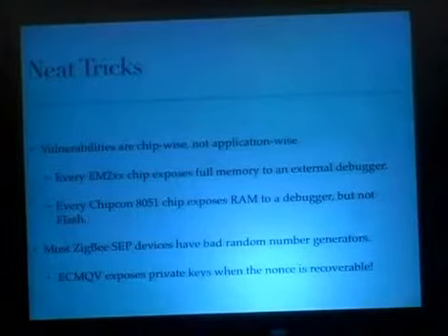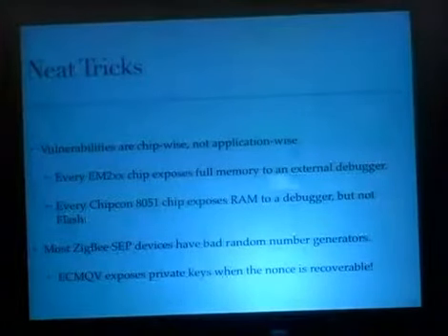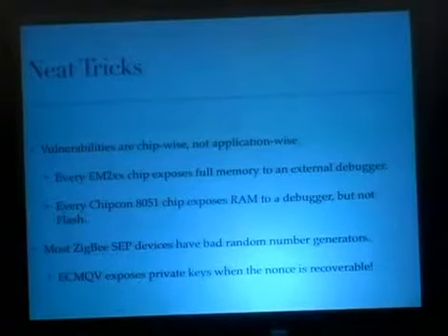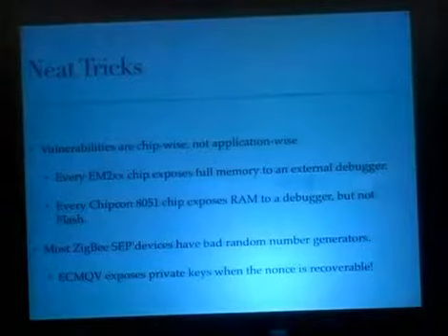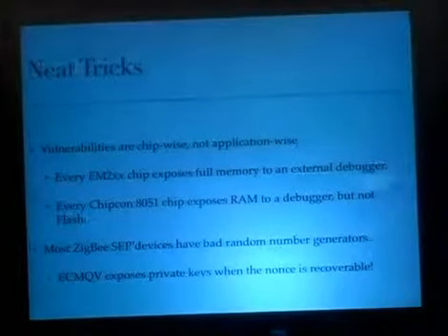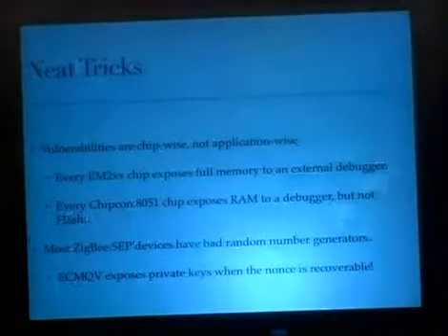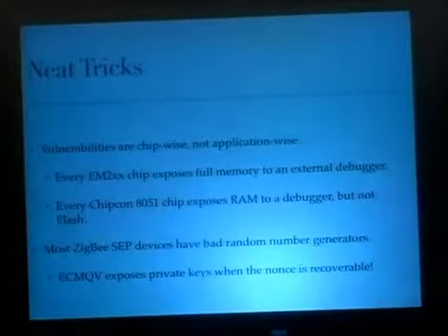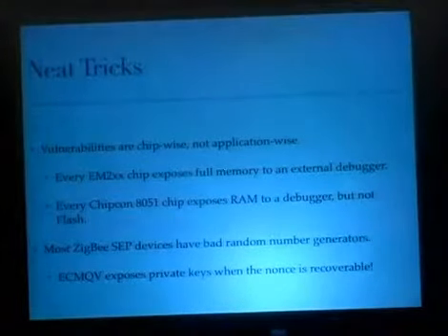All of the ChipCon 8051 devices, including the Girltech IMME, protect their RAM from a debugger, but they don't protect flash. So you can connect to a chip and erase it, and then copy RAM out, and have a copy of all of the radio configurations, including keys and channels, encodings, all of that other stuff.